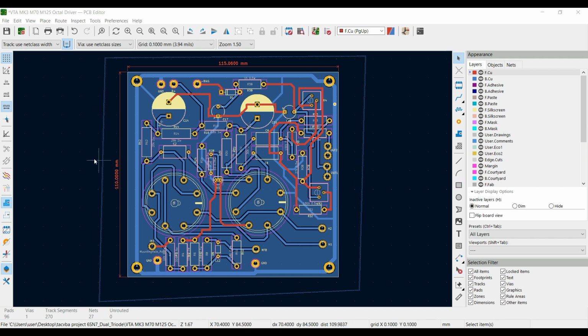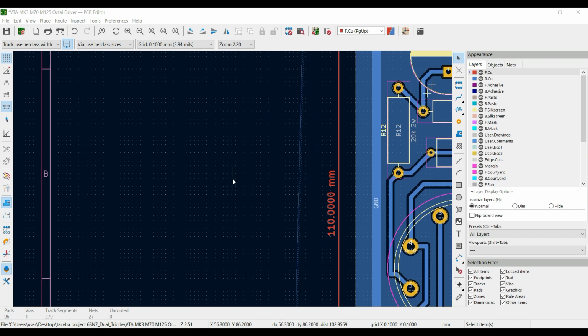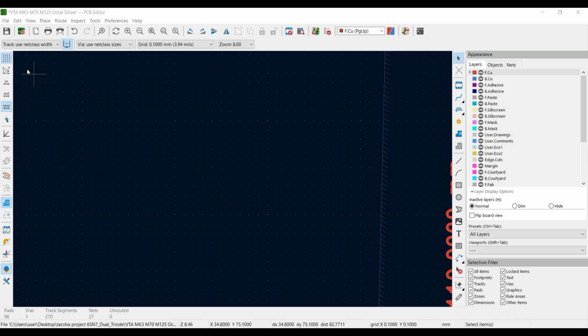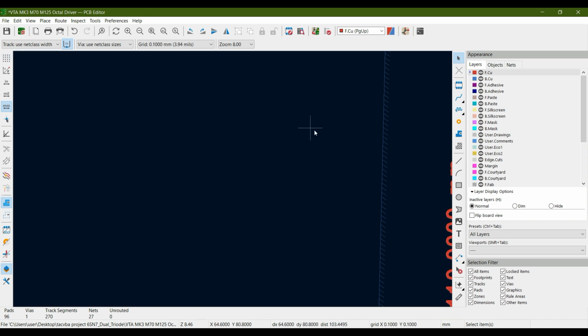So let's just start by discussing. The first setting is about the grid. Over here you can see you can display the background grid in this edit window. These are grid dots in the background. You can switch them on and off by just clicking over here. Now you can see that there are no grids present. If you click on this, you can see your grid over here.